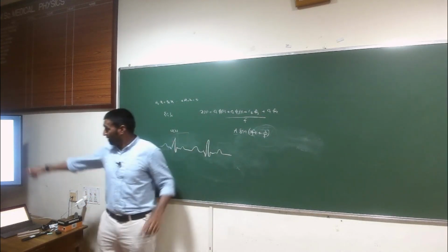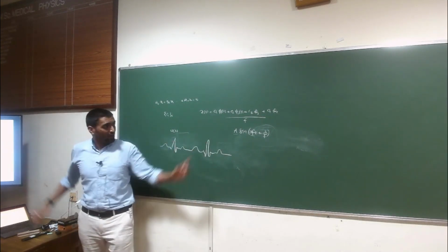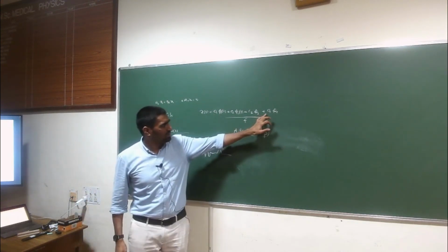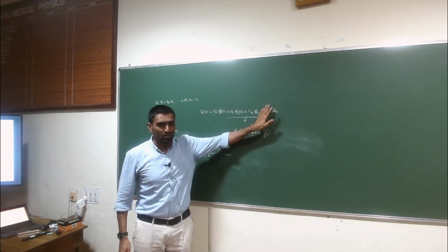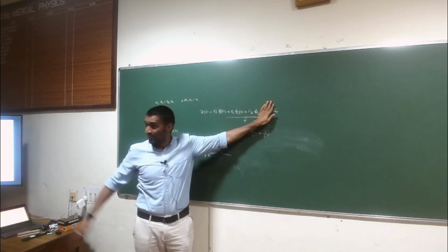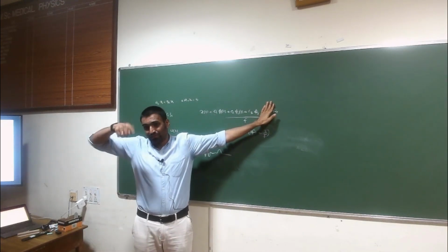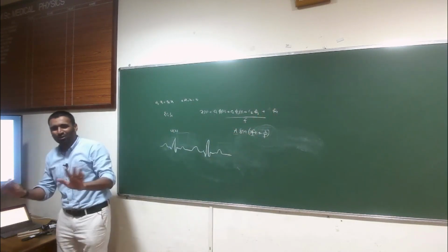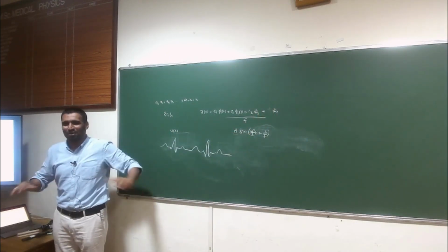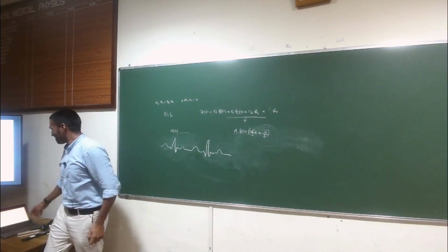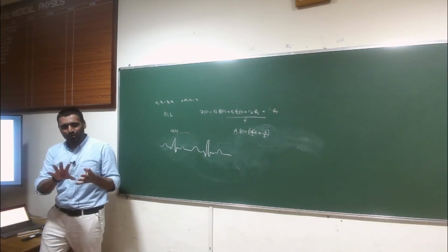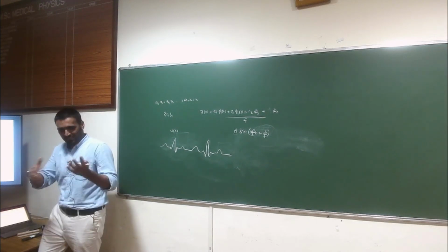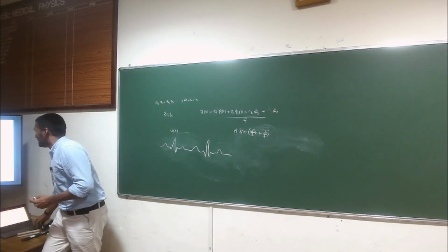Now, if I want to remove the high frequency component, how would you remove it here? All you'd have to do is make C4 0 and then reconstruct just this. Then you'd find that the fast varying component disappears. If it's not clear, don't worry, it will become clear hopefully. Being able to look at a signal from a different perspective makes some of these things easier to deal with. That's the point I'm trying to get across.